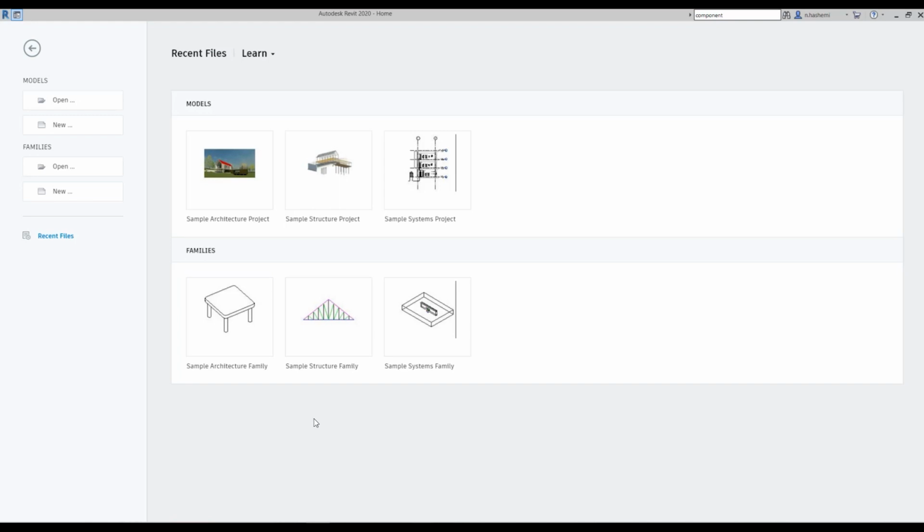Okay, so if you create a 3D model but do not apply a specific material to it, what Revit does is that it will actually use the category material if you have assigned any material to that specific category. Okay, so you may or may not assign a material to a category.